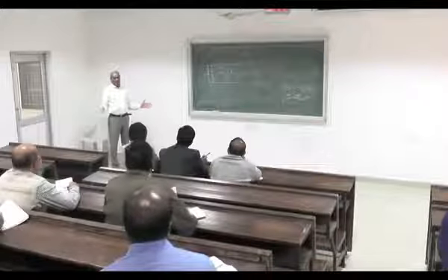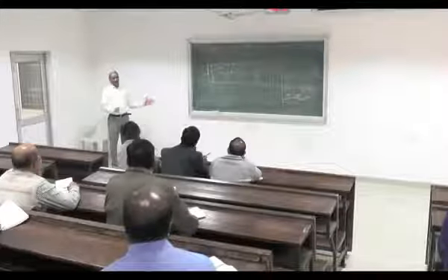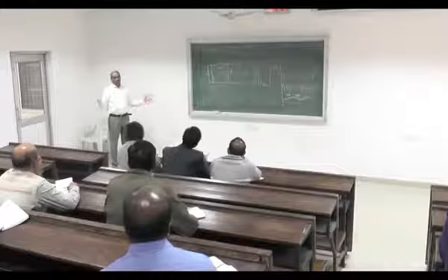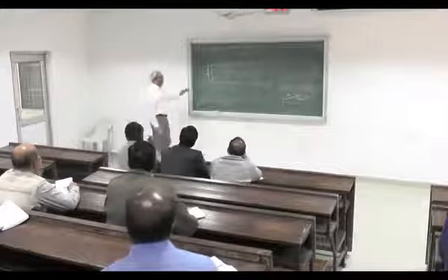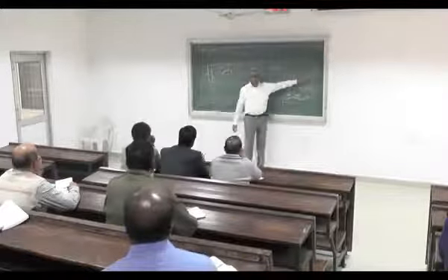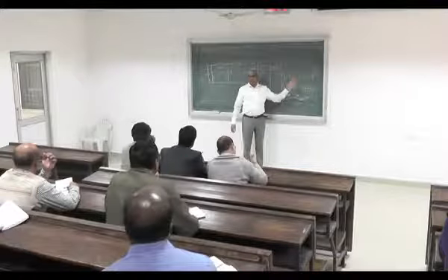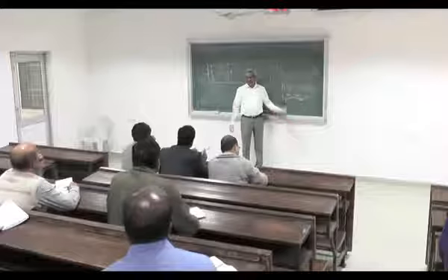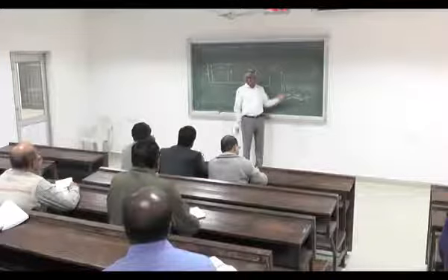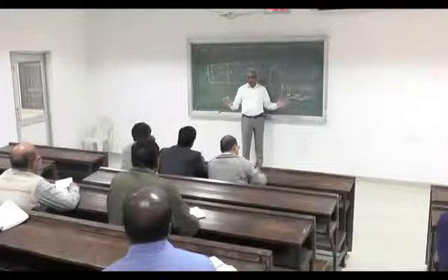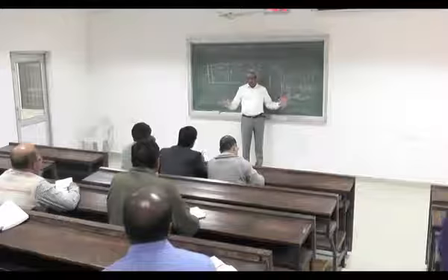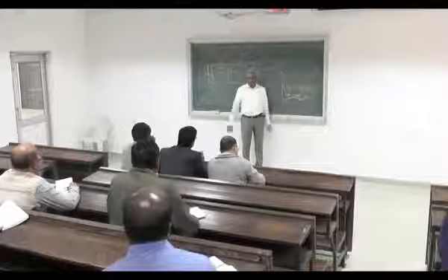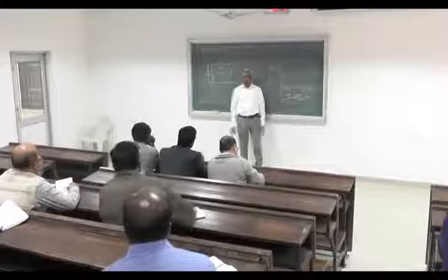So now you look at it differently: how many cycles of this current are you going to have, and then you select that number of cycles that you want. So 10% means, let's say if you have 100 cycles for the full duty cycle, for 10% you have 10 cycles. So that's the only difference.